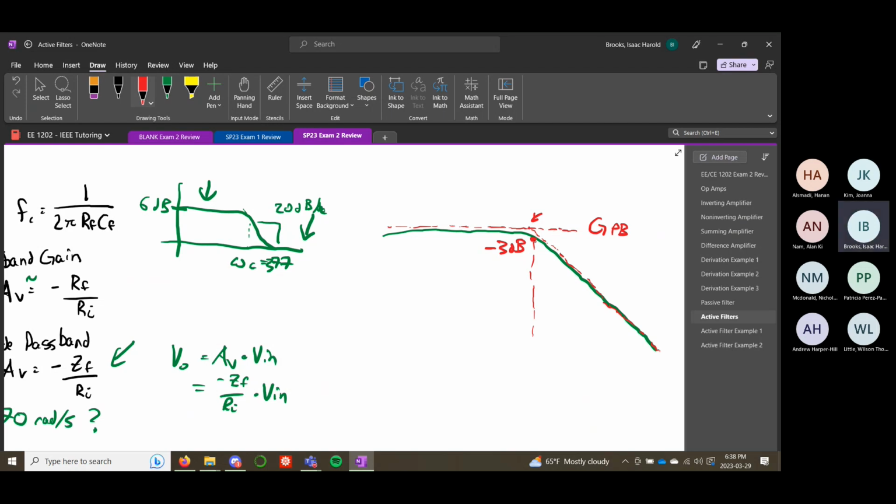So say that we are at our cutoff frequency, and let's say that that is 1 kilohertz. And let's just say that this is a 0 dB filter. Okay, 0 dB means no gain. If we were to look at the log formula, this would be 20 times the log base 10 of 1. Our gain ratio would be 1. The log of 1 is 0. So that's how we would get 0 dB, when your ratio is 1.